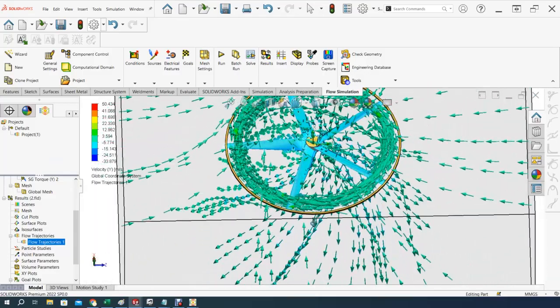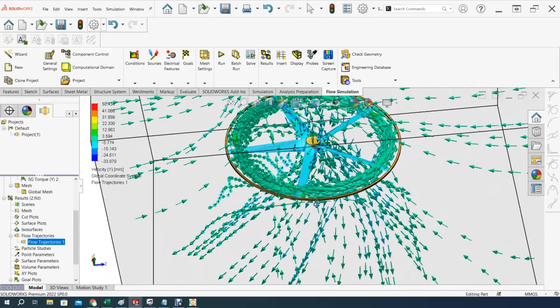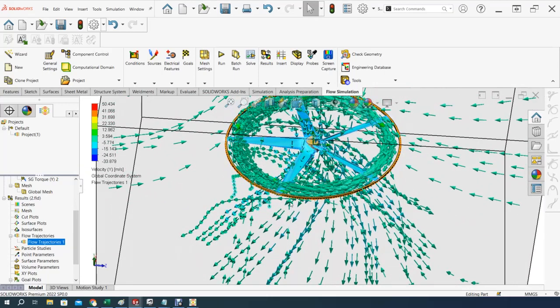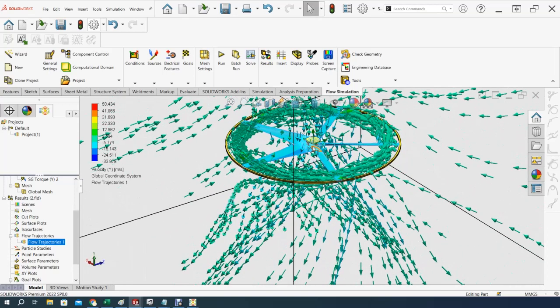Interesting. You can see not much pushing air down at the tip, and that's not good. Meaning that when I designed this tip, I remember 35 degrees is way at the root, but at the tip there is not much of it, and there's a lot of energy lost right here. So I should have provided some curvature, so that it doesn't end here at 0 degrees.